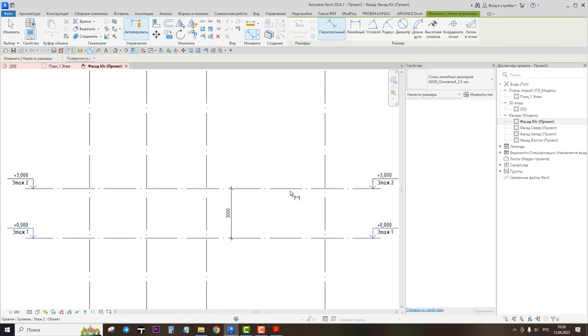Actually, try to calculate and understand this height in the beginning. Consult with the client or with the builder, or calculate it and decide on your own. You are the planner, right? Changing this level height at the end of the modeling might bring you a lot of trouble, actually. Okay, we have 2 levels, it's enough.